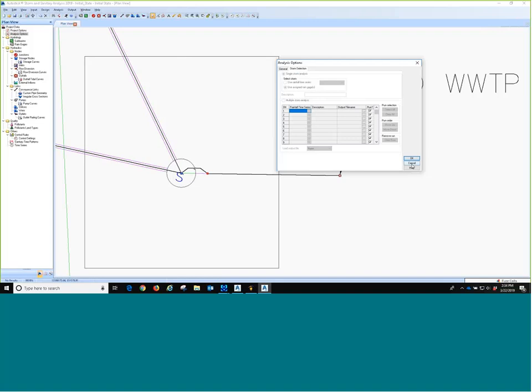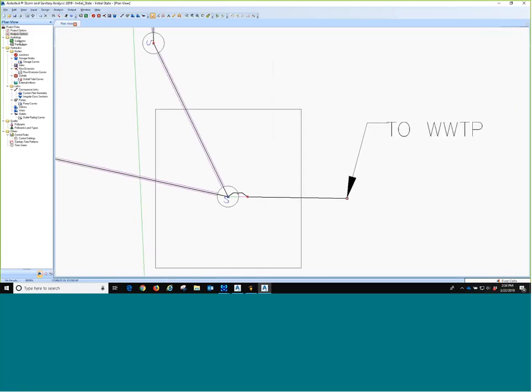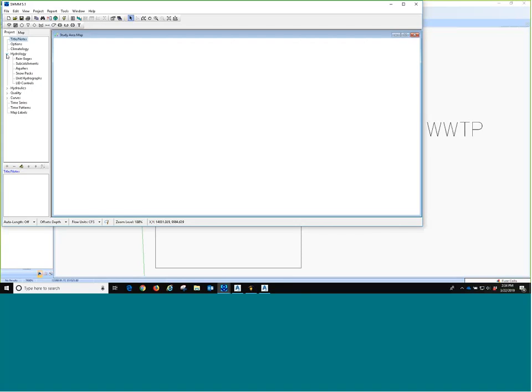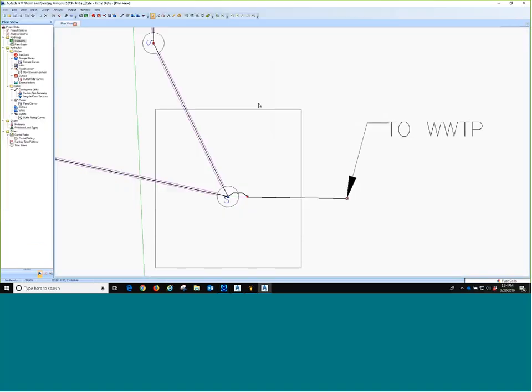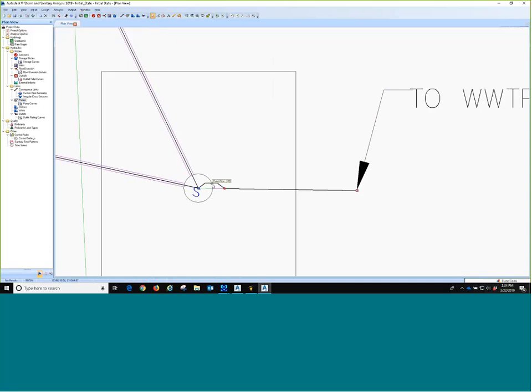That should be fine. We're not using any rainfall dependent infiltration. If this were a combined sewer system, I could also model it that way and include sub-basin areas, which I think are called sub-catchments in SWMM. Let's see. Yes. Do that and then drain them into specific nodes, or I could have additional catch basins go to it. So I really can blow this out as much as I want. All right, one last look before I finally click an initial run.